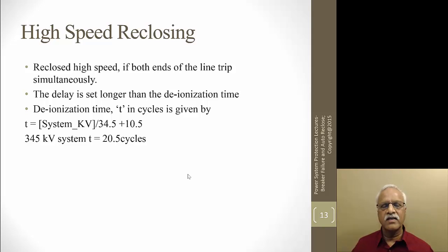But there are some cases where it is a permanent fault, a 3-phase fault, and reclosing on a permanent fault is dangerous. So we disable high-speed reclosing for a 3-phase fault, or disable reclosing completely for a 3-phase fault.